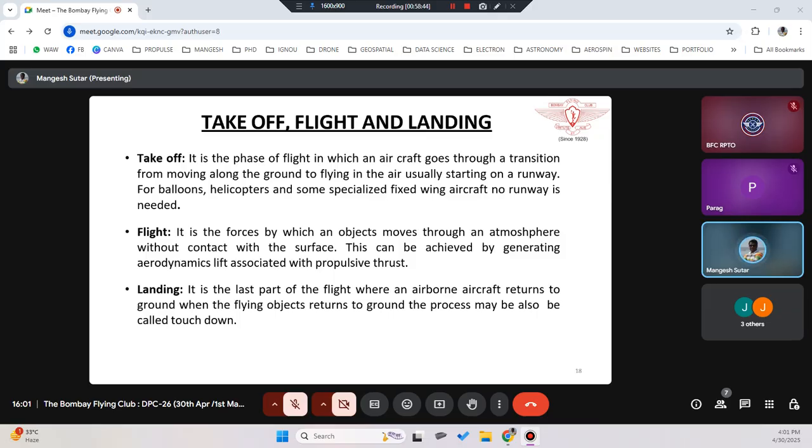Okay, so we have to make sure, because of RTL, we need to know how to put the drone into RTL mode, and then it has to go into RTL mode and it has to land. Even though it is automatically landing the drone, that is very crucial, because even during automatic landing, mishaps can happen. So you need to observe and monitor continuously. In case the RTL is not happening properly or there is an issue, you should be able to break that sequence.